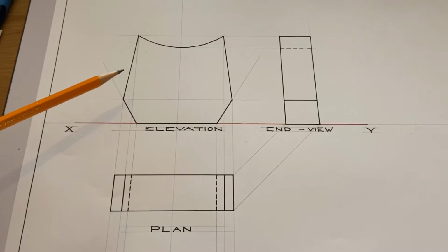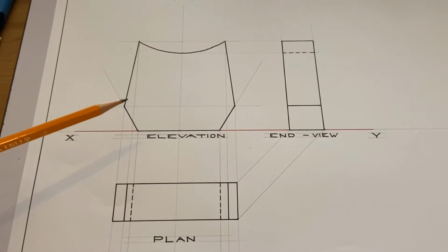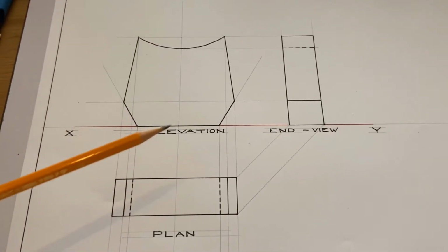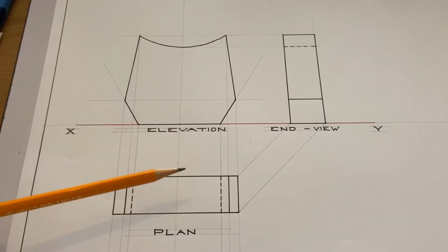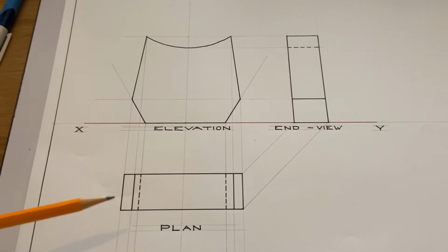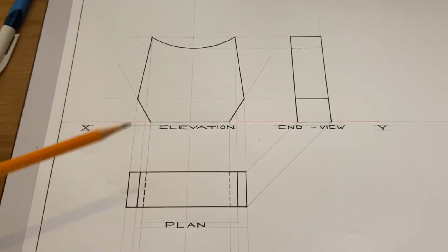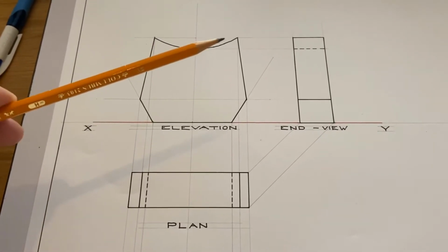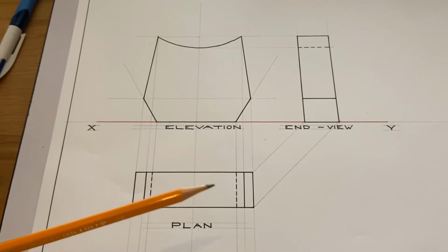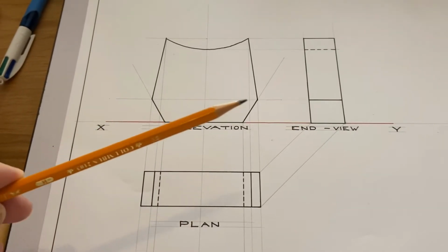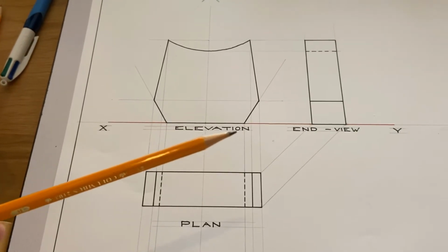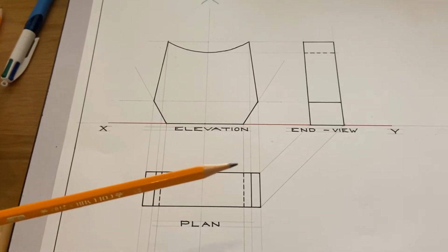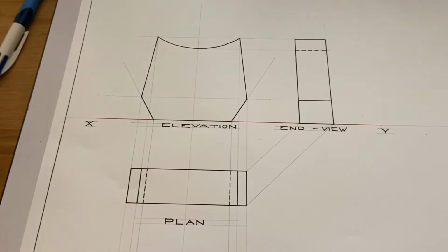Once we have the elevation drawn, again we project our lines down into plan. The plan, we're told, has a depth of 25 millimeters, so we mark 25 millimeters and draw the plan. Again, the top two corners, you will see those, so they'll give you a heavy line. These outside edges give you the end of the plan, and these corners underneath that can't be seen will be represented by dashed lines for the hidden detail.